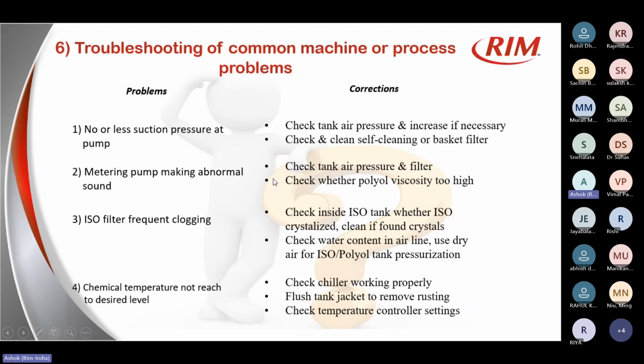Metering pump making abnormal sound. This is also related to tank pressure, as I just mentioned in the first point. So tank pressure and the filter have to be checked. Polyol viscosity also has to be checked, because if the polyol is too viscous, the pump can also make abnormal sound.